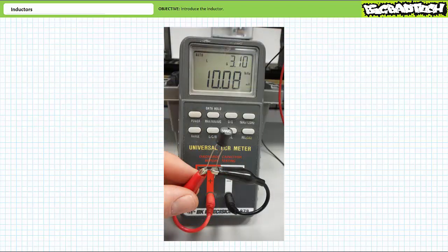Here's an inductor with a code 106C written on the top. It is way too small to be a 10 million microhenry or 10 henry inductor, so I'm presuming this manufacturer is using a different code where 10 is the two-digit inductance value and 6 indicates the number of zeros following this number, where the units are now assumed to be picohenries instead of microhenries. 10 with 6 zeros is 10 million picohenries, which would be best expressed as 10 millihenries. The LCR meter says 10.1 millihenries, super close to the anticipated nominal value of 10 millihenries.